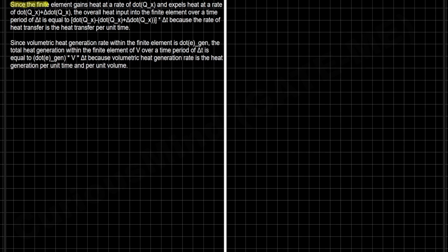Since the finite element gains heat at a rate of q̇x and expels heat at a rate of q̇x plus Δq̇x, the overall heat input into the finite element over a time period of Δt is equal to this expression.